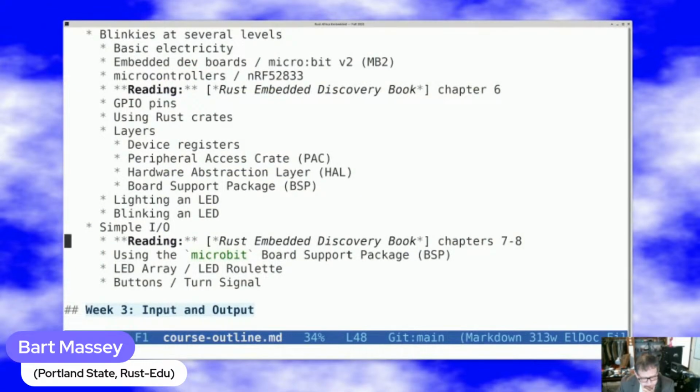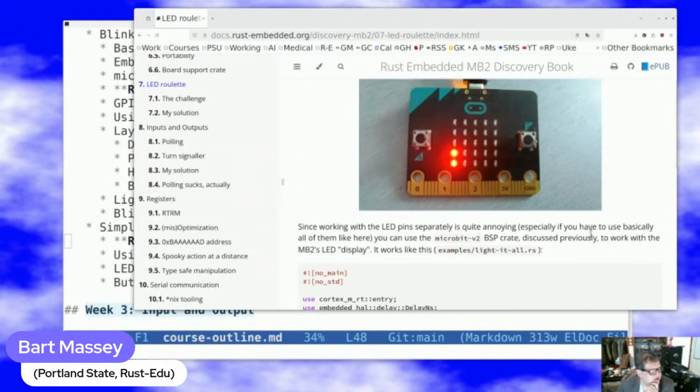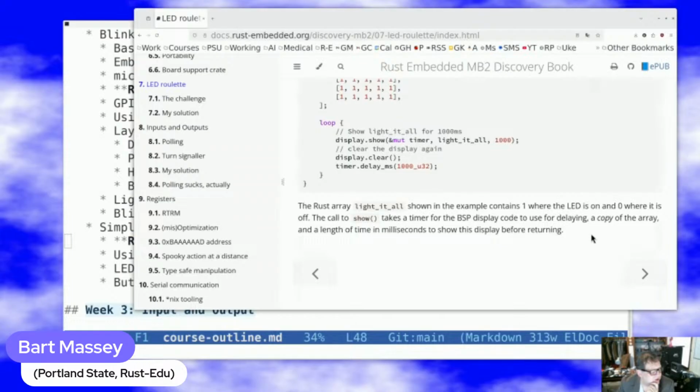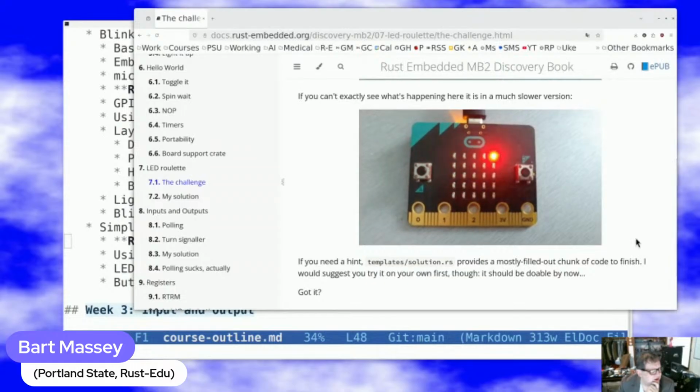If we look at what we were trying to do, let's see right here. There should be a slowed down version somewhere, I think. Maybe not. I can't remember. Yeah, you can see what's going on here. We just pick one LED at a time and light it up like that. But, of course, it's a pain in the neck to do that, because now I have to have control of all the row and column pins, and I have to figure out which one to turn on when. But I can do it, and when I do that, then I can make the display do something interesting.